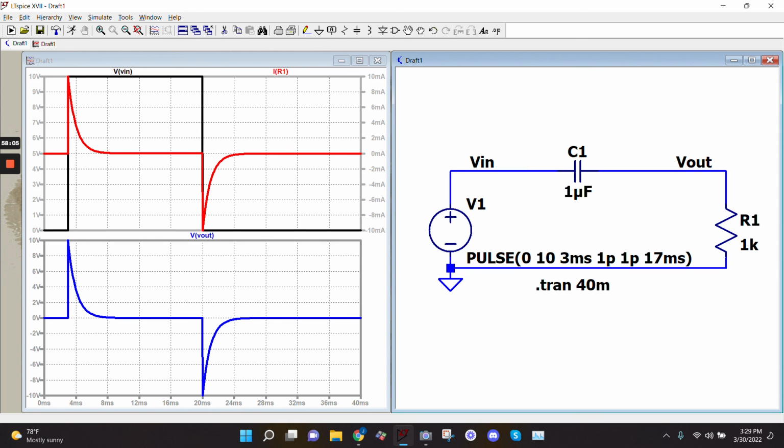But say you have a capacitor on a PCB or circuit board, and it's not connected to any actual resistor in there. It's just sitting on the board somewhere, and it was charged for some reason. The board around it might be like 10 megaohms of resistance or some huge resistance. So the discharge time will be several seconds, and you'll see it. That's why. But if it's actually connected to a resistor, like in this case, you wouldn't see it. It'll just go off immediately.